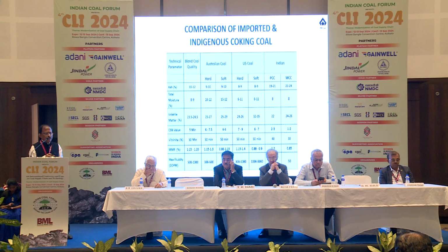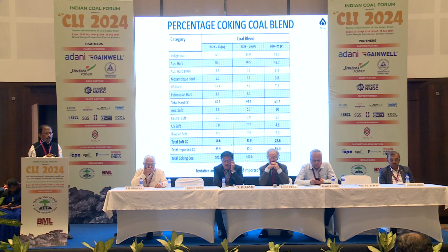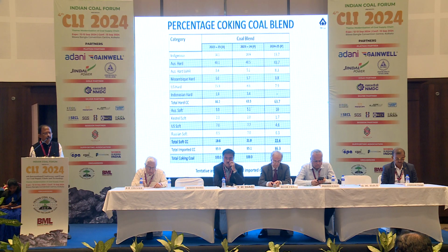It's a comparison of the different properties, and I'm skipping this slide. As for the percentage of coking coal in the blend, we are using mostly Australian hard coal, around 43% in the blend. We use a blend of different types of coals, and that is charged in the coke ovens to get our coke, which can meet the requirement of the blast furnace.